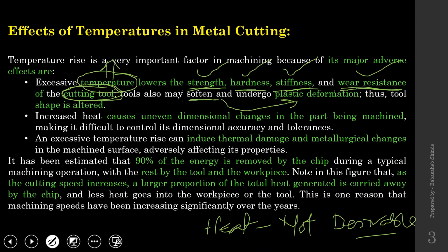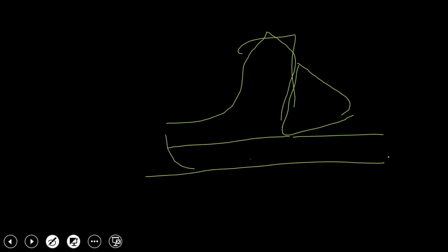we know that whenever temperature increases, it is going to expand the material. When you heat it, it will expand. When you cool it, it is going to contract, right? Now, additionally, as I said, this heat distribution, if this is a single point cutting tool and this is the workpiece that I am machining, this whole thing is not going to be exposed to the same temperature.